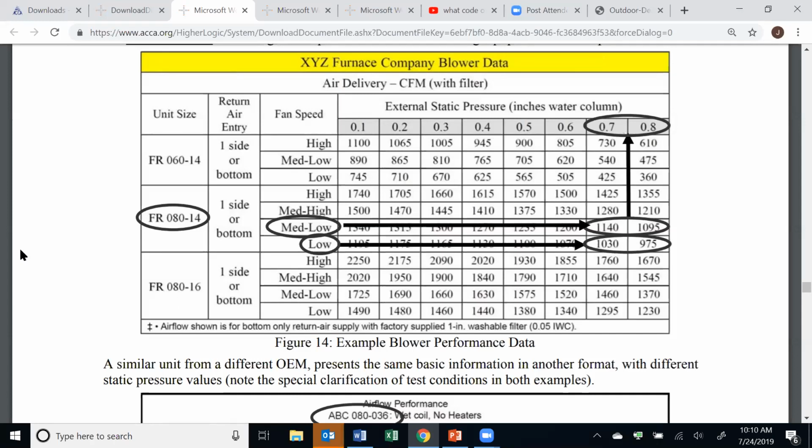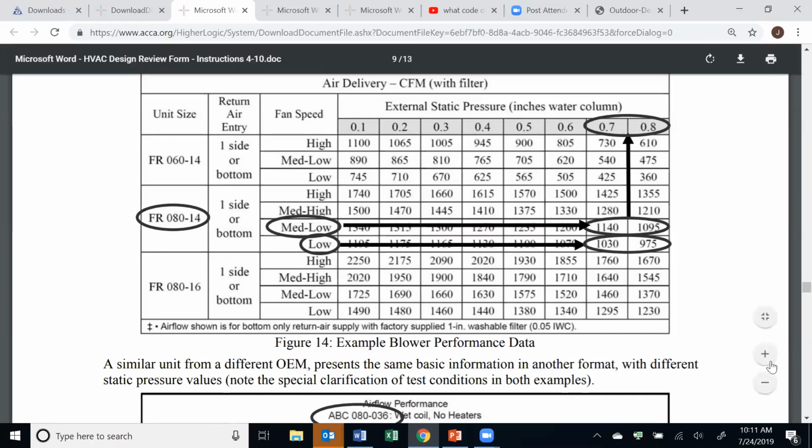If you're in a dry climate and you see low airflows, say around 350 CFM per ton or lower, that's also a problem. Those are some things a code official could look for, or if they see them, have that conversation with the contractor and understand why they decided to take that step.